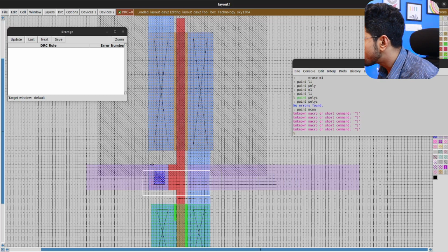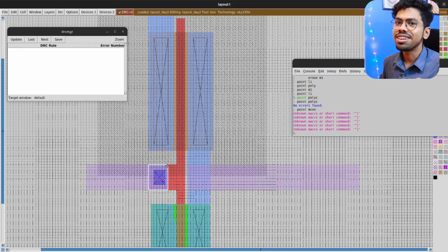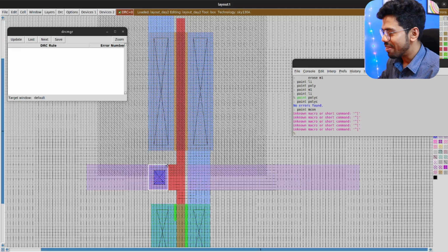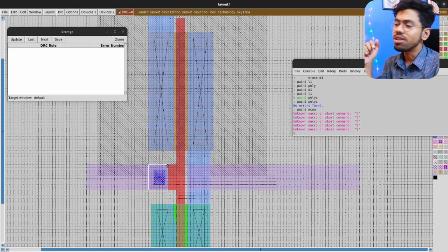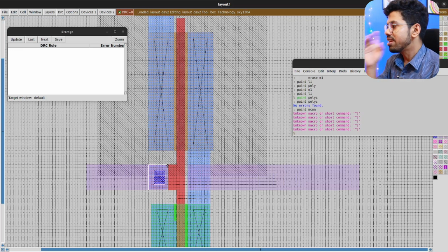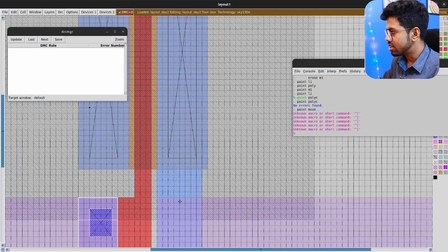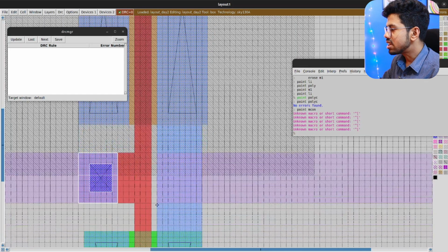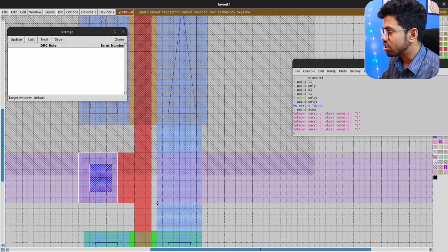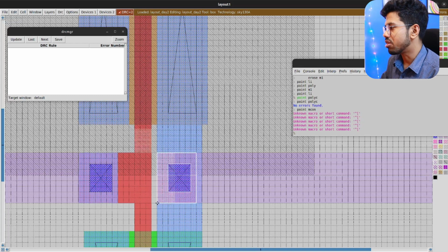Now I want to copy this fellow to here. To do that, I need to select a box. I did the same thing in the last lecture, you know it, right? Then you need to press A on your keyboard. Pressed A, and then you need to get your cursor. Let me zoom in if I can. Yeah, get your cursor, place it roughly somewhere where you need to place this copied thing, and then press C on your keyboard, and we got it.